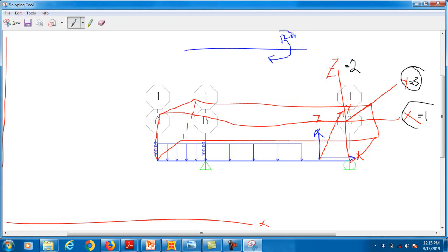You need to understand that the direction of the moment is clockwise, so the value we insert in the window has a positive sign. One thing you must remember: if this moment is applied in an anti-clockwise direction, you will insert the value with a negative sign. But the question is about what axis the moment is applied, because whenever we apply a moment, it must be applied about an axis.